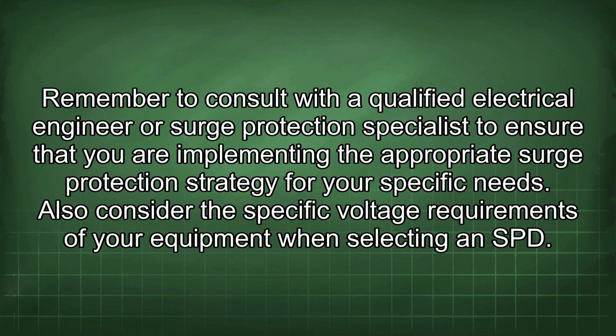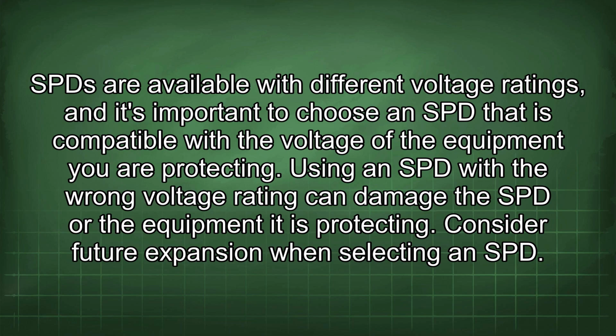Also consider the specific voltage requirements of your equipment when selecting an SPD. SPD are available with different voltage ratings, and it's important to choose an SPD that is compatible with the voltage of the equipment you are protecting. Using an SPD with the wrong voltage rating can damage the SPD or the equipment it is protecting.